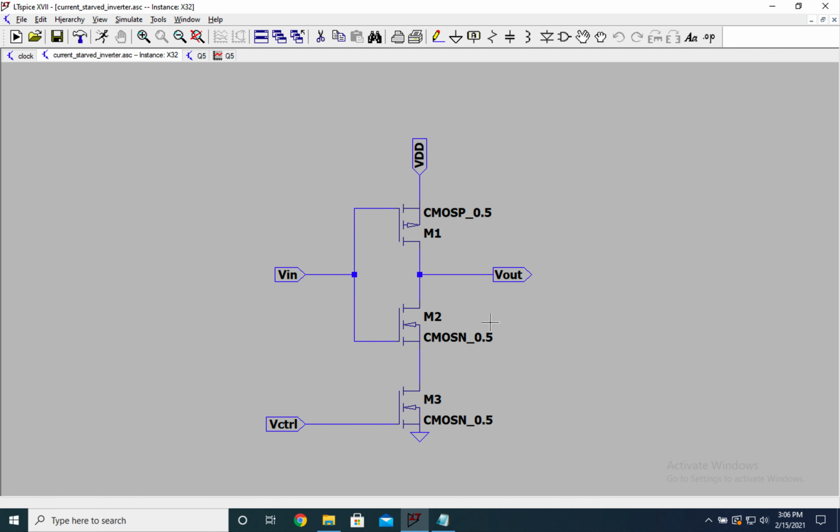So you can see the top 2/3 of this circuit is a CMOS inverter, standard like we've been seeing it. But now we've added an additional NMOS between Vout, the first NMOS of the inverter, and ground. And we've actually allowed for an independent gate voltage to be applied to this NMOS. What this does is, before, if we just had the inverter, we would get a fixed current discharge to ground when this input changes from, what would that be, low to high, I believe.